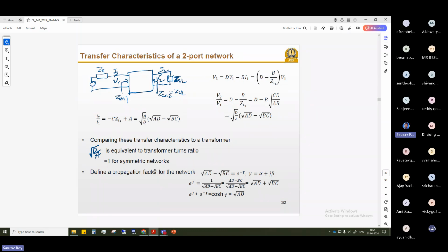And for another answer to the question, if you look into the Pozar book, there is a transfer matrix using which you can convert the ABCD matrix to S parameters or vice versa. You can even convert Z and Y parameters to the S parameter matrix and vice versa.